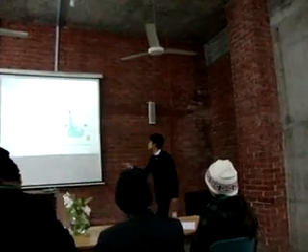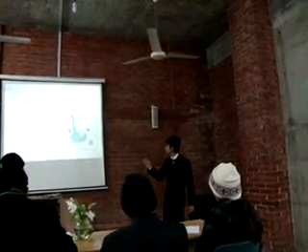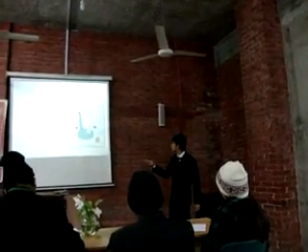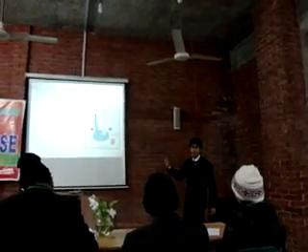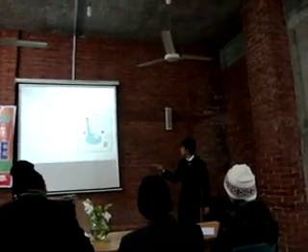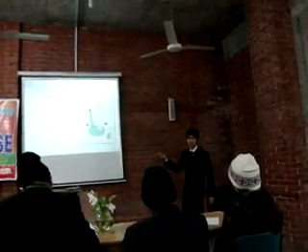This sensor has a preset value. We just put 5 kPa as the preset value for the pressure sensor. When 5 kPa is reached, this device transmits a signal.